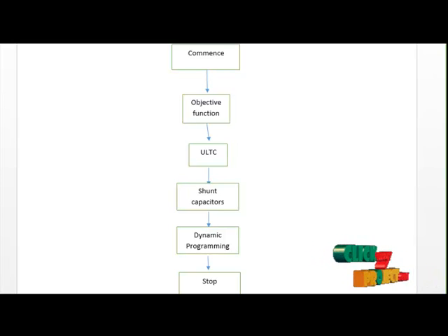A switchable shunt may be disconnected from the circuit when conditions warrant, while a fixed shunt is permanently connected to the power line. Shunt capacitor banks are mainly installed to provide capacitive reactive compensation or power factor correction. They are installed near the load terminals, in factory substations and receiving stations, to provide leading volt ampere reactive.